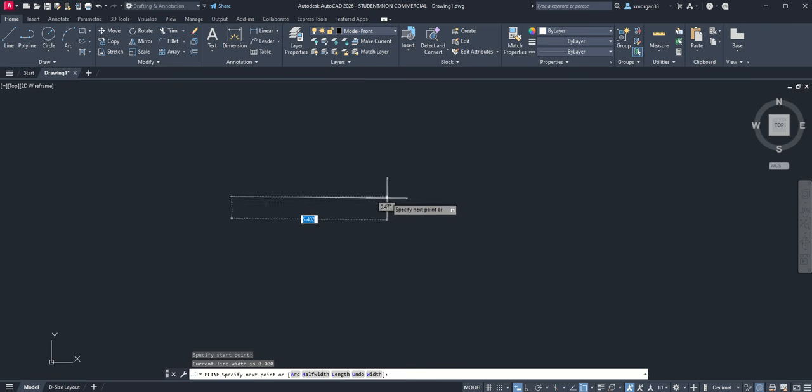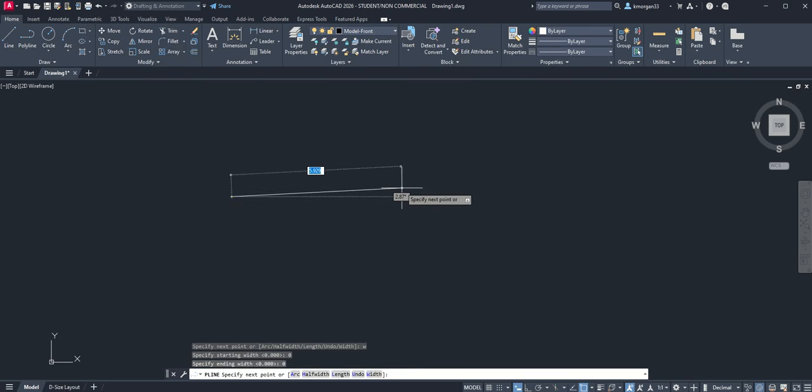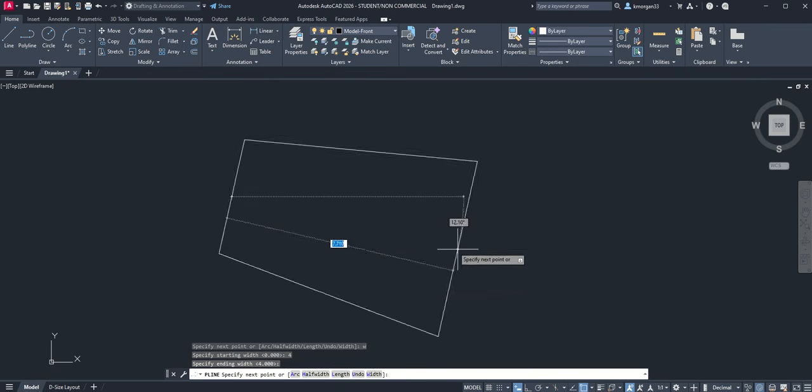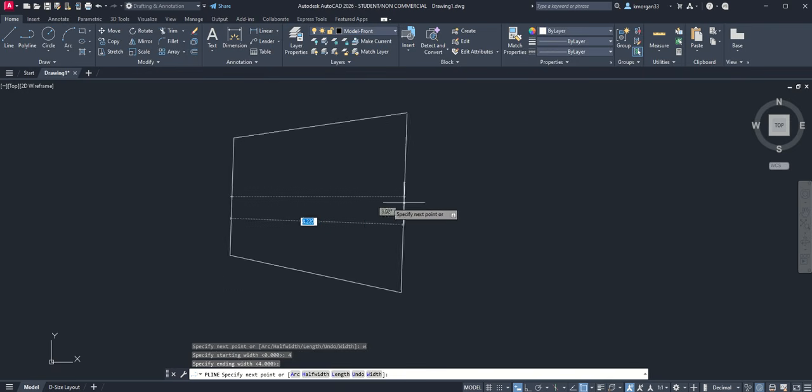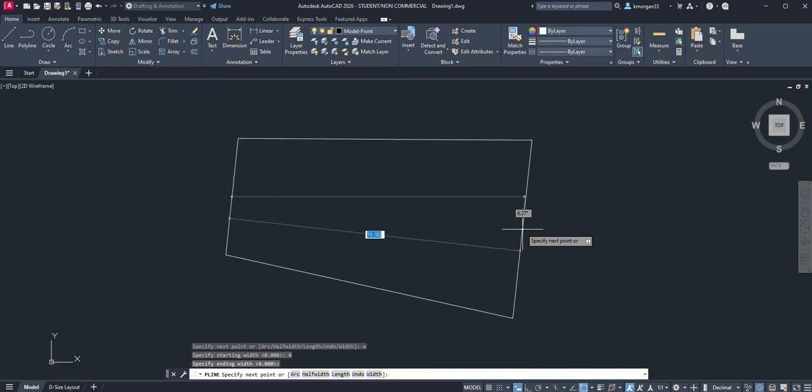So if you get into the width mode, make sure you go back and give it: enter, W, enter, 0, enter, 0, enter. We'll get back to the 0. Otherwise, it's going to stay fat. I was showing you how to change the width to 4. If you do that, look at this, the width is now 4 wherever you go.